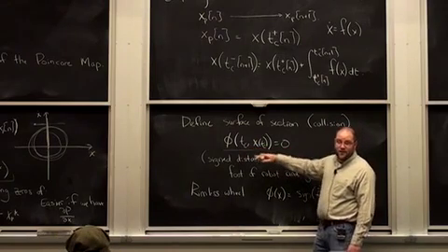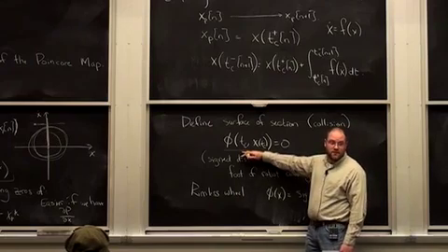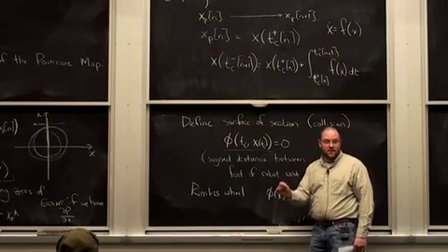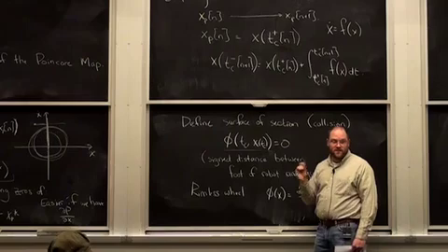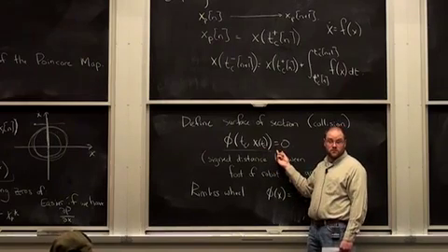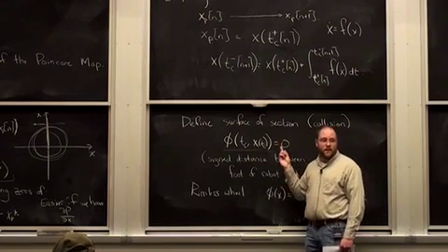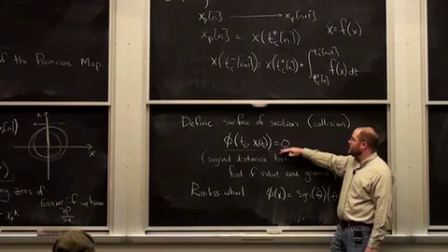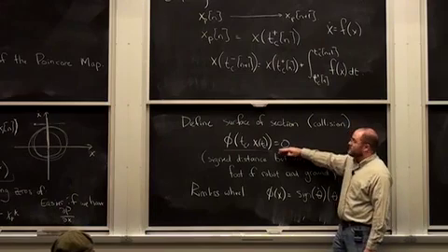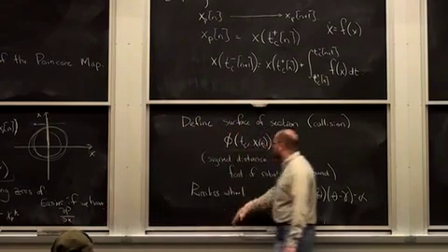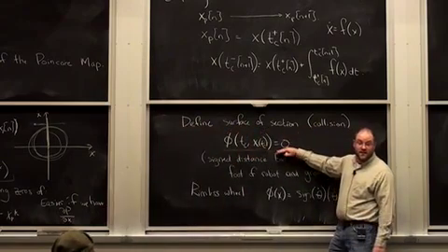And you can hand as your options to the ODE solvers in MATLAB event functions like this. And they will very carefully watch for a crossing of that event function across 0, and pinpoint the time and state at which that thing goes across 0. So this is a very common notation in hybrid systems worlds. Turns out if we do care about finding this gradient of the Poincare map, then this is going to also be the enabling thing which allows us to compute that gradient.